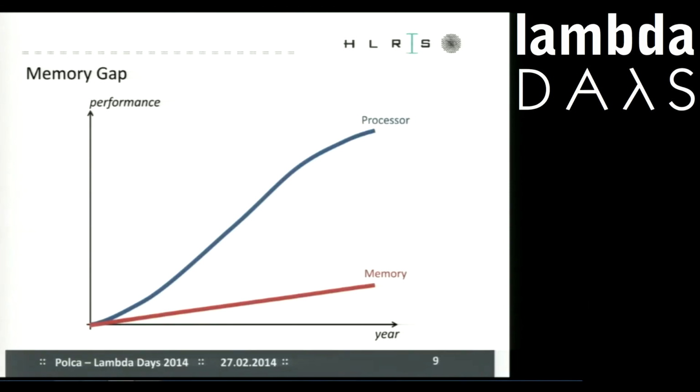Yeah, and one of the problems also is that it gets worse over time because we were not able to evolve memory at the same speed as the CPUs. They are able to deliver a lot more data, but the latency, that is the time since you request the data till you start getting them, is still extremely high. Even if we are adding more and more cache, the problem with cache is that when you increase the size, to be able to have more data near the CPU, that's something you can do now with smaller technology, it also becomes slower. It also increases the latency.